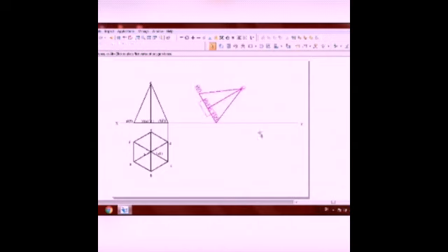Now draw the projection lines. Of course, we can move the whole solid a little closer so that we can get space for the next front view. Oh, the multiple copy should be switched off before doing this. Yeah, switch it off and then move the particular view closer to the previous view. Be careful, if it is too close, then the lines will overlap. There must be some gap.